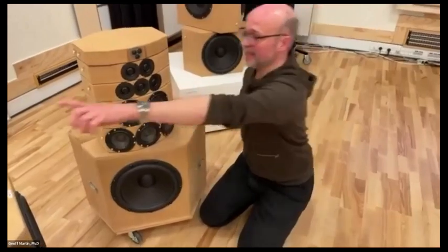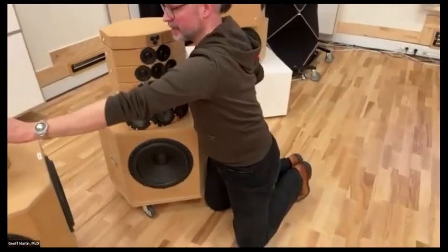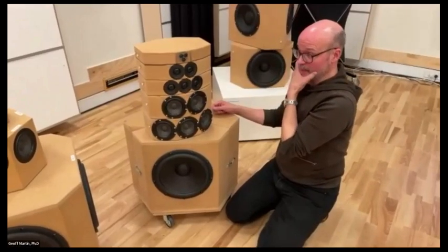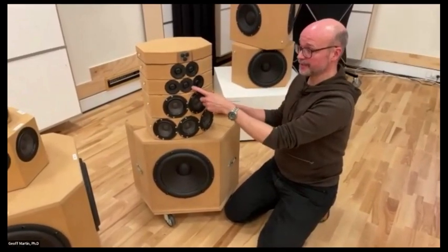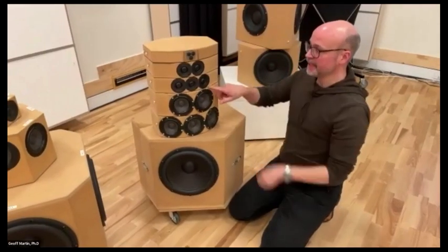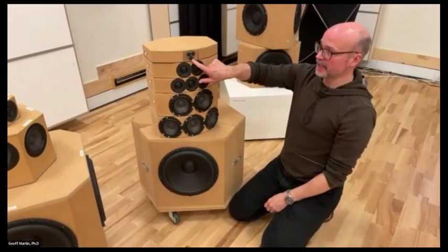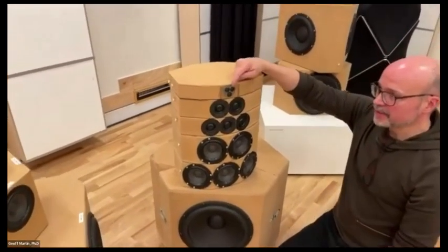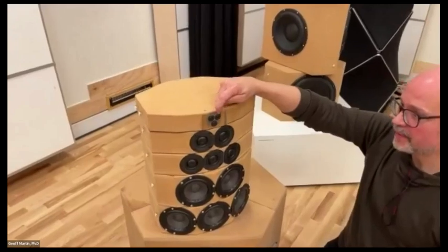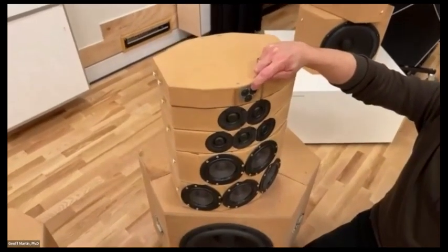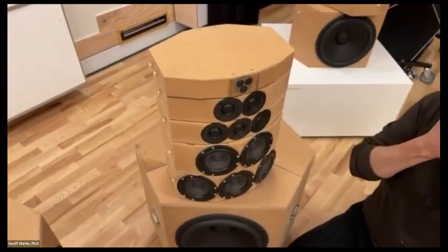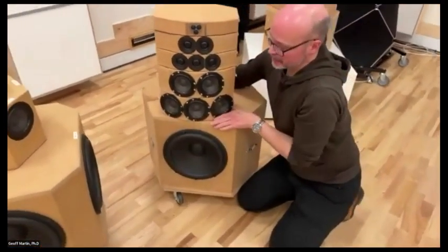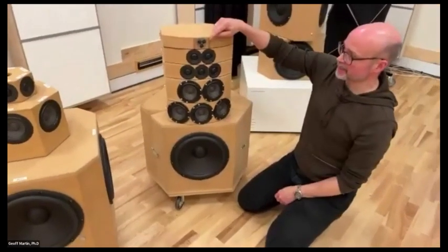What we also found when we made the previous version with the rotating speaker was that these 1.5-inch tweeters, although they behave really well up to about 10 kilohertz, we started losing control of them from about 10K and up, roughly. And so we started looking into the option of getting a super tweeter. Some people would call it that, we would just call it a tweeter. This is an 8mm dome tweeter that we had made as a prototype. This never got put in any speaker, but we kept the prototypes. We still have a couple lying around. And that let us take care of the directivity from about 10 kilohertz and up.